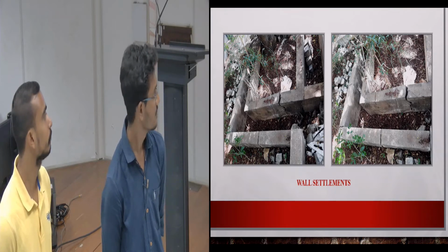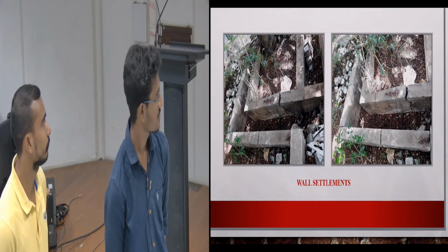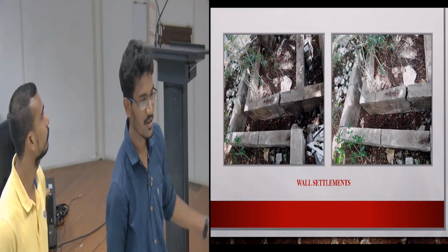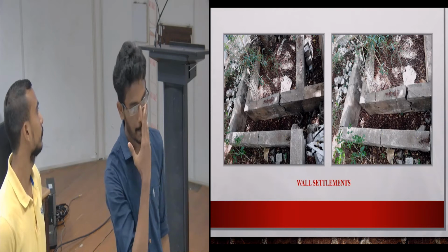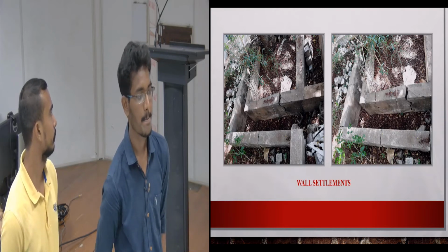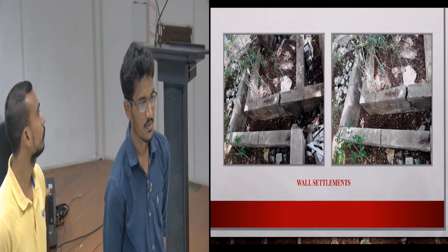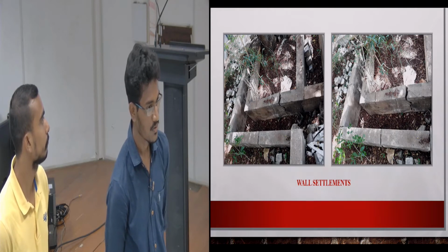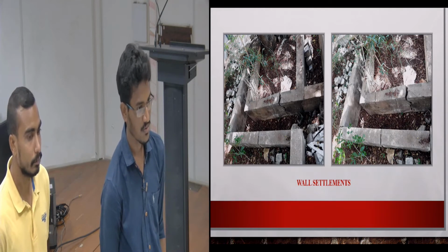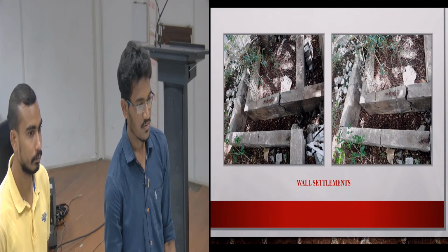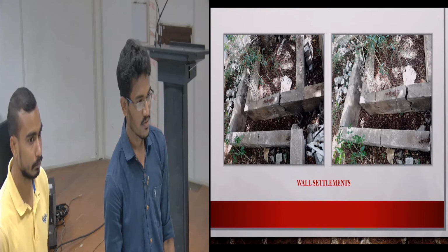Second thing is, I understand what you're saying, differential settlement, because you see the crack settlement, and it opens up this way, right? But differential settlement, when you're talking about buildings, did you go in and measure, is this thing level? Is it tilting because part of it is already going into the soil? Why is it going into the soil?